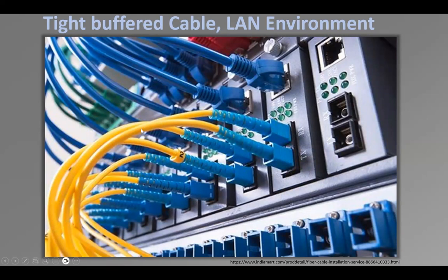well, tight buffered cable. Now, these cables are yellow, patch cables are yellow, which tells me that these are single mode patch cords. If they were orange or aqua, they would be multi-mode. And we'll go over the color coding a little bit.